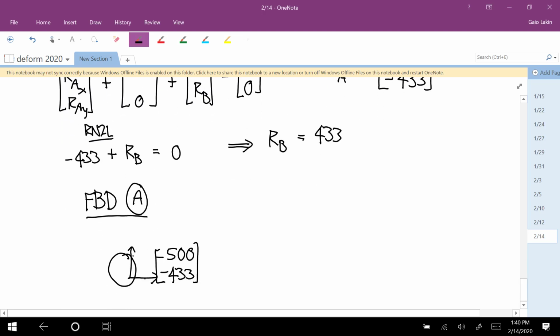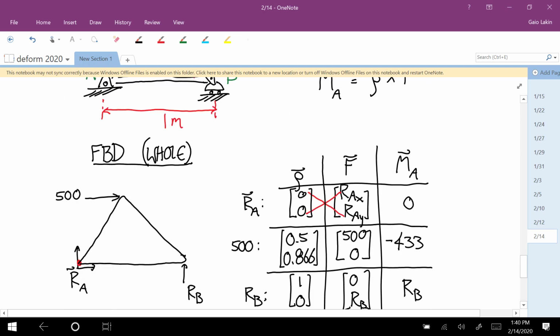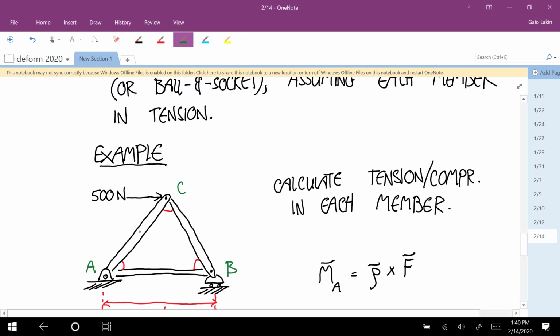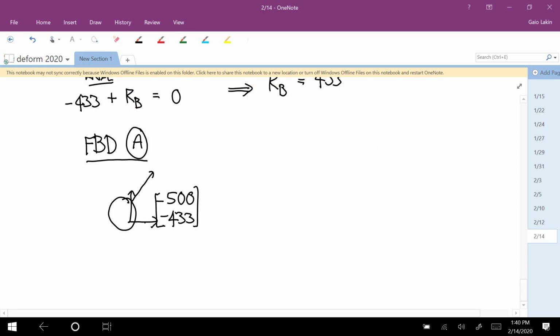And then we have a tension coming from member, well, I guess we have to name these two. Let's call this 1, 2, 3. So if member 1 is pulling on that joint A, then there's a force this way that we'll call F1. And if member 2 is in tension, there's a force this way that I'll call F2. And since we're treating this like a particle, we don't have to deal with moments or anything. We just have to use force equilibrium.